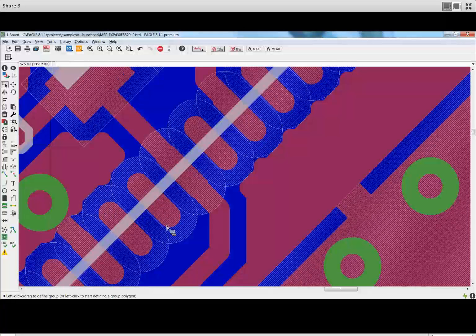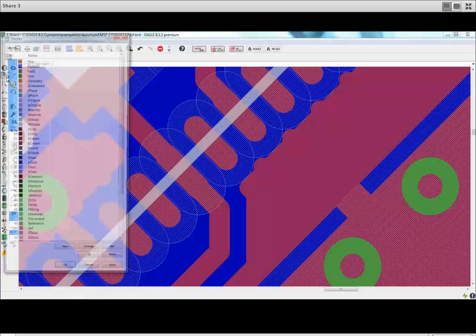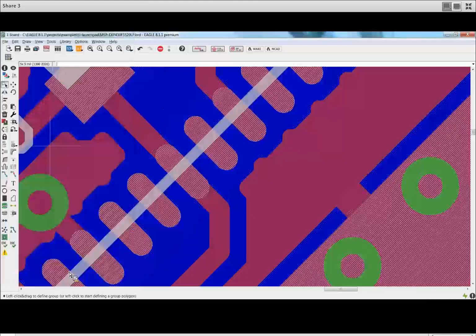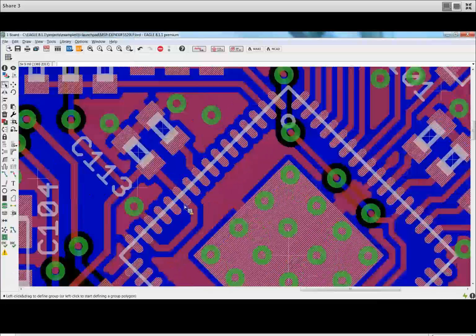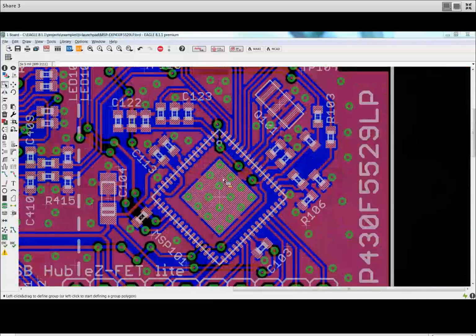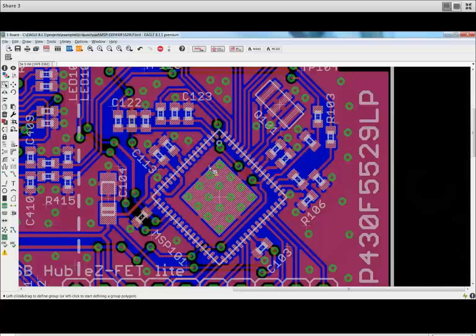And that's why usually for SMD parts, the cream layer is the one that takes precedence for your layers, okay? Now, this takes care of DRC. We're basically done with any DRC. If you have any questions, go ahead and post it on the chat group, please. Now let's go through the post-processing.